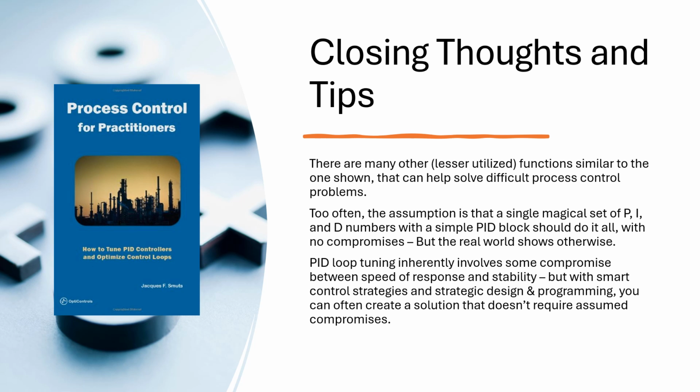Analog controls, like I say, there's always going to be these compromises between speed, stability, minimizing errors, etc. But if you're smart about it and you really look and you understand the controller that you're working with, the logic, and understand the system, watch the operators, talk to the operators, understand how to operate the system optimally, you can often find solutions that are a little more than just a simple PID block, but it's going to run way better.